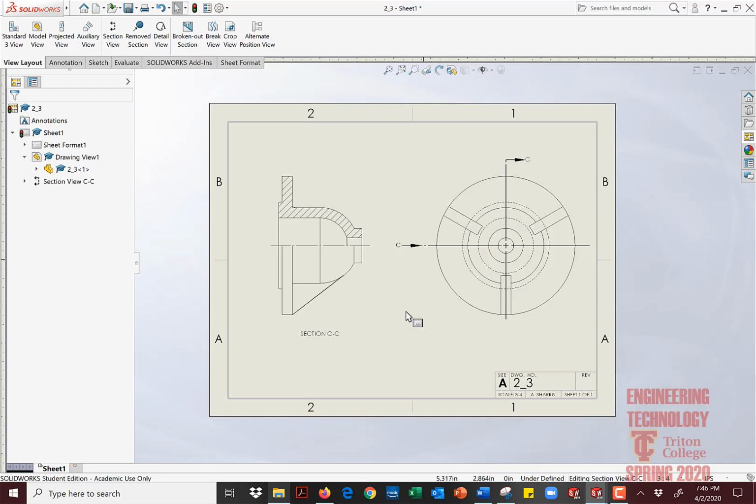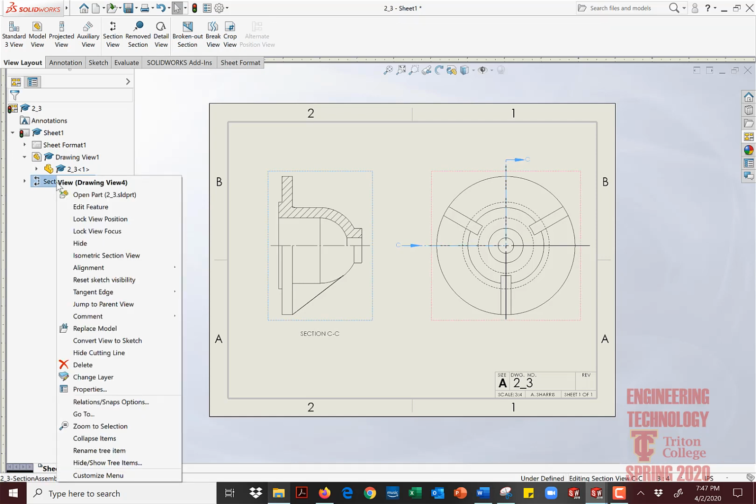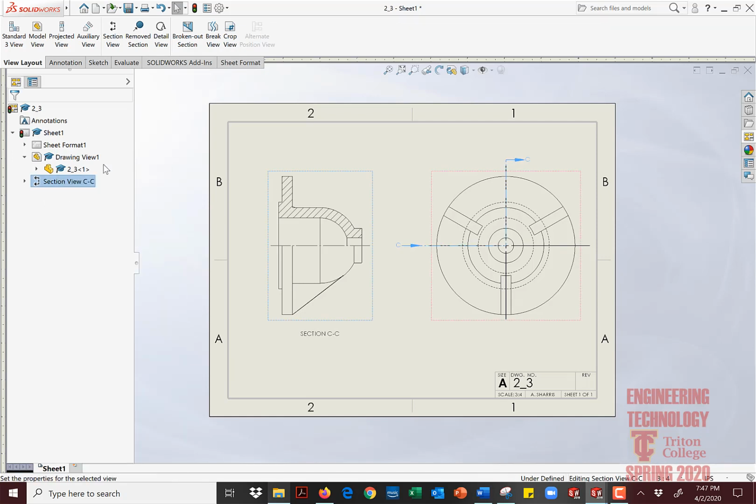So what's wrong? You need to remember not to make too many sectional views by accident, or number two, because they do happen, correct your sectional views to the correct letter designation that you want that sectional view to be. In this case, we want it to be section AA, not CC. So you want to make sure you remember to correct that.